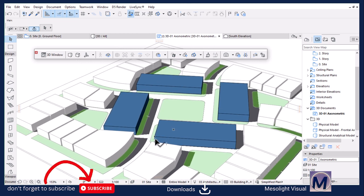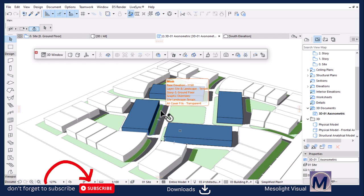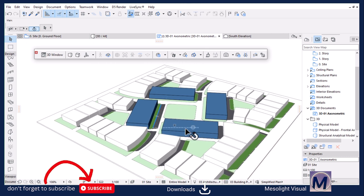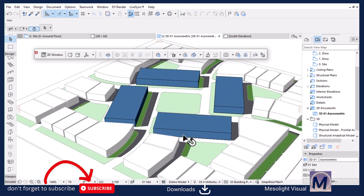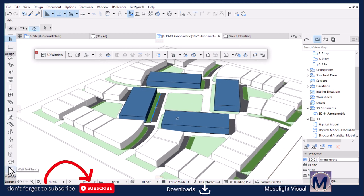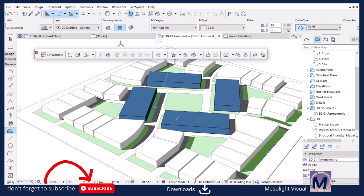Okay, from here now I want us to understand the outline. We're going to use the outline to call out our commercial plot by using a heavy outline on the massing. To do that, we're going to use a fill tool this time around. We're only using 2D information to inform, because we don't have a parametric control for this kind of situation. So I'm going to go to the documents, tools, and find the fill tool.